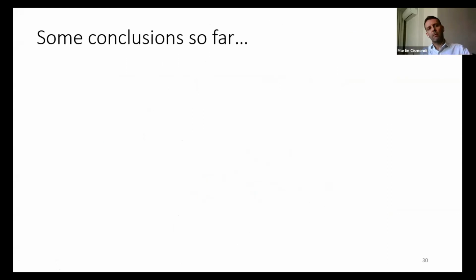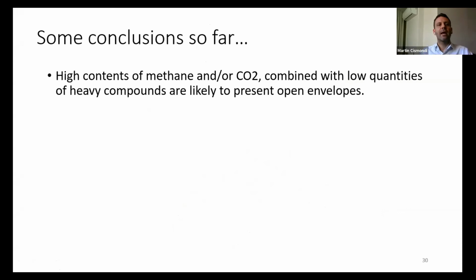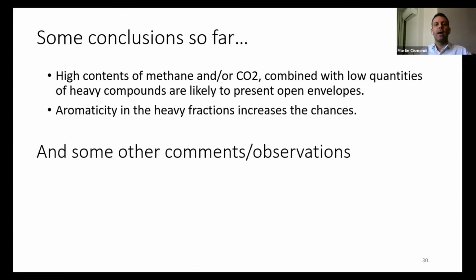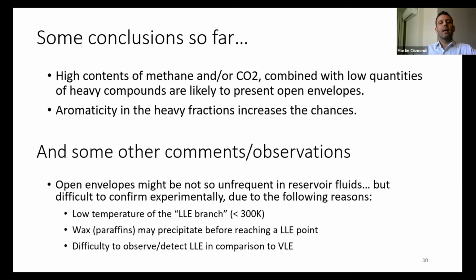So some partial conclusions so far are that high contents of methane and/or CO2 combined with low quantities of heavy compounds are likely to present open envelopes. Aromaticity in the heavy fractions also increases the chances. And some other observation I would like to make is that open envelopes might not be so infrequent in reservoir fluids, but they are difficult to confirm experimentally for the following reasons.